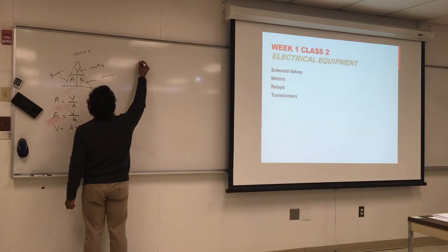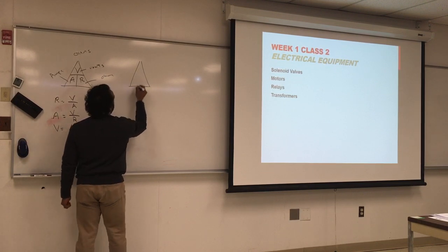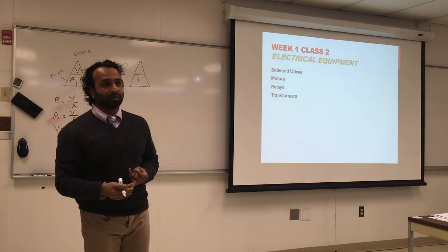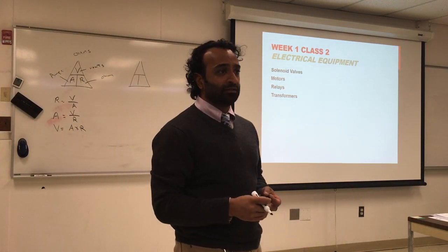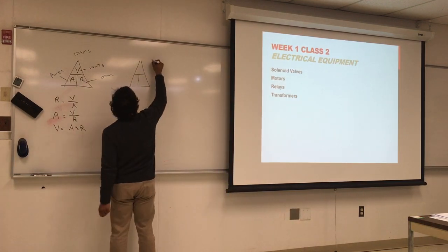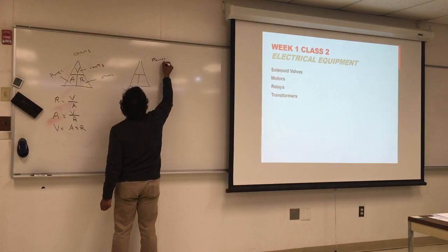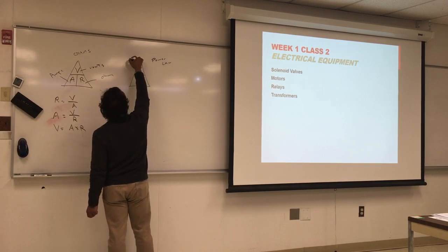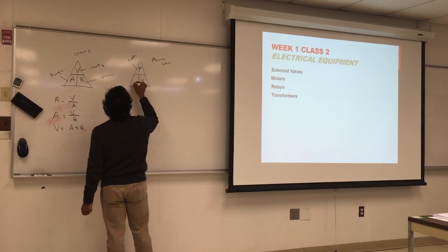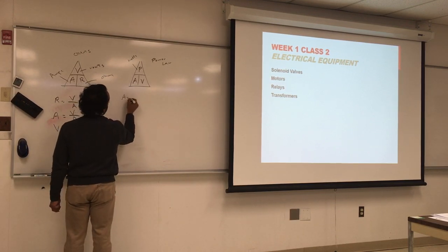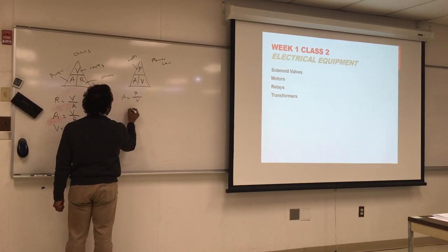Second thing is power law. That's important also to calculate cost, to calculate how much power you're going to be withdrawing, see if the circuit can handle the amperage draw or not. So that's the power law here. Power is in what unit? Watts. Voltage and amperage. Same thing goes. Amperage is power over voltage.